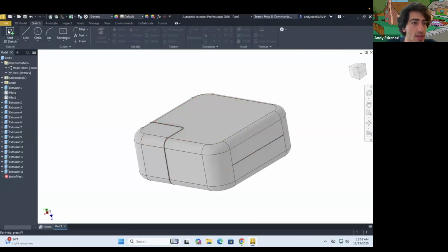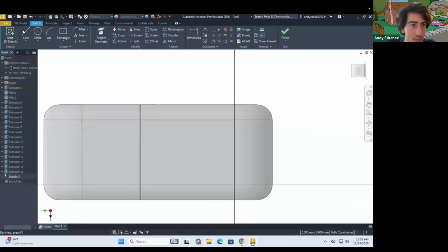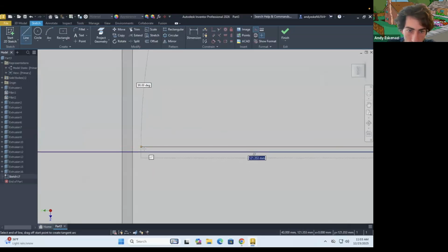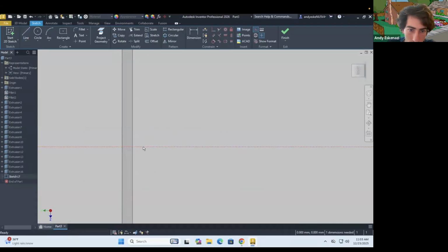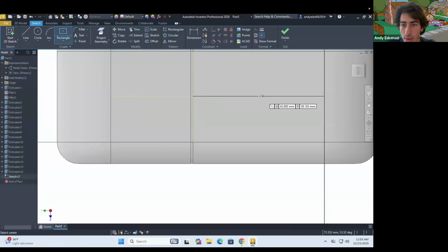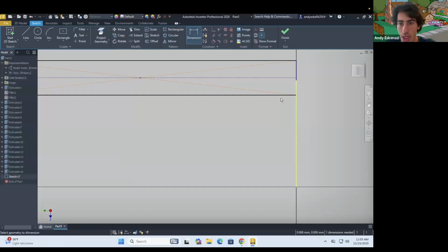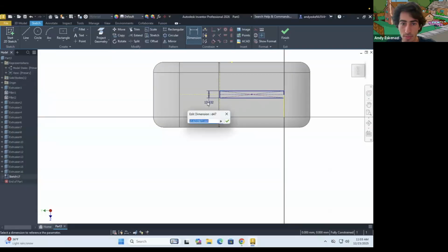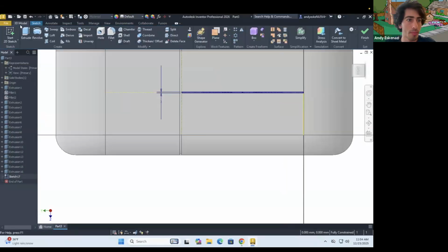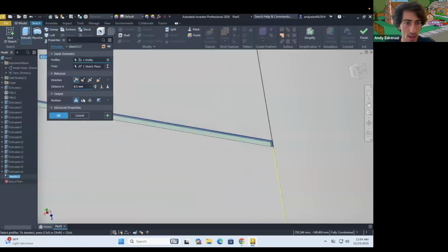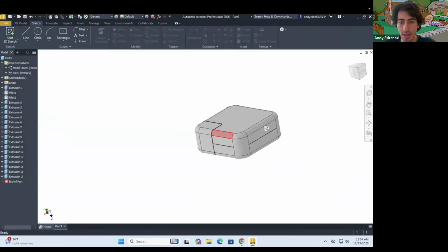And now one last final sketch on this face. That's really the meaning of this design. Okay, we're gonna go all the way up here. We'll choose that point, control that line, coincident. There we go. Rectangle, that's gonna go like that. Now letter D. That's gonna be 1 millimeter. Good. And we're gonna cut it like that. Okay, so we got all of our sides.